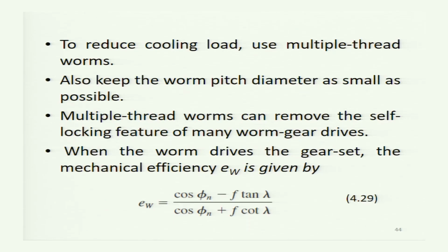To reduce cooling load, use multiple thread worms, because for that the efficiency will be more and a lesser amount of heat will be dissipated. Also keep the worm pitch diameter as small as possible. Multiple start thread worms can remove the self-locking feature of many worm gear drives.